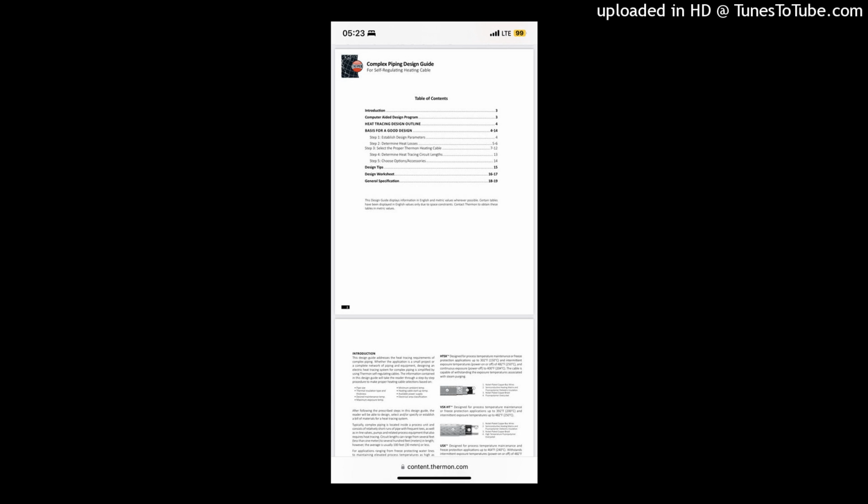Determine heat tracing circuit lengths based on cable selection, electrical design, and pipe lengths with allowances for valves, pumps, supports, other equipment, circuit fabrication and splice kits.